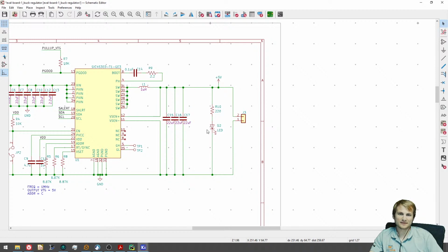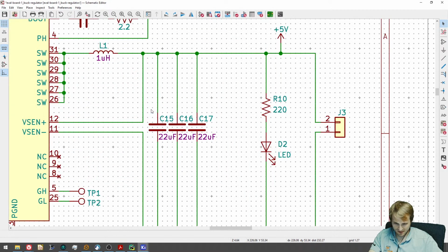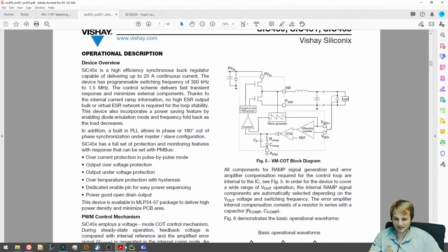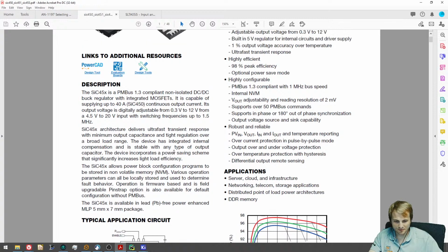But if it's just kind of a steady state load with a half an amp, 2 amp transients, it should be fine. But more so than adding more 22 mic, just because I think they're wrong. I don't see under what planet they would require 6 of these unless the data sheet is misleading us and it has to be low ESR, which they explicitly also say in the description.